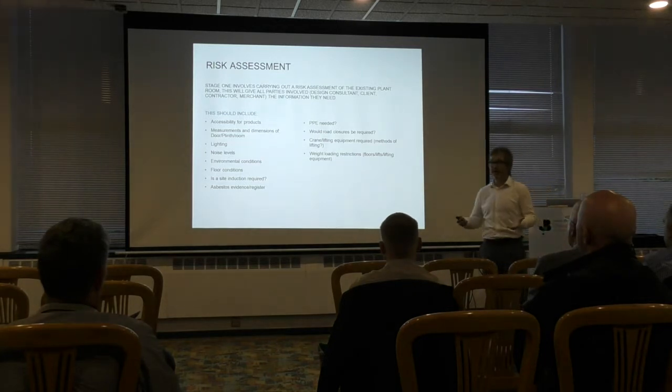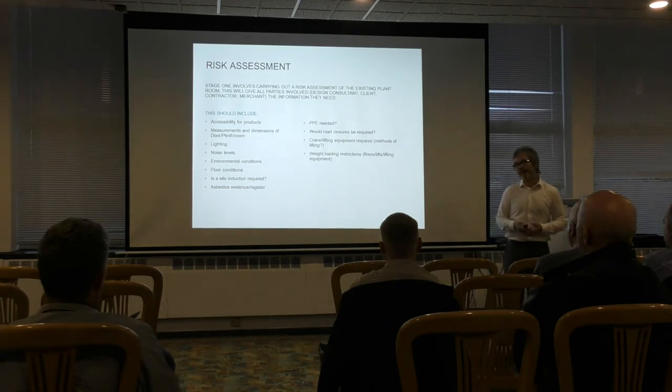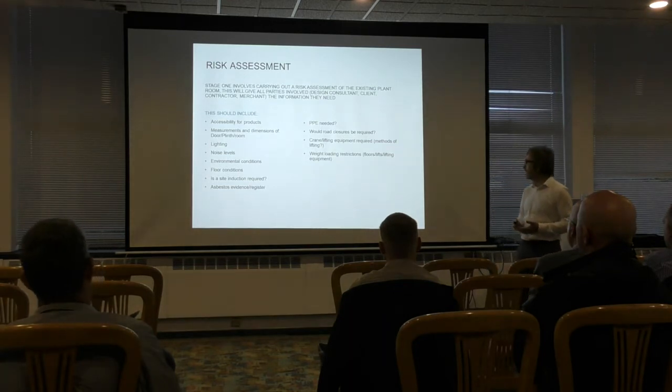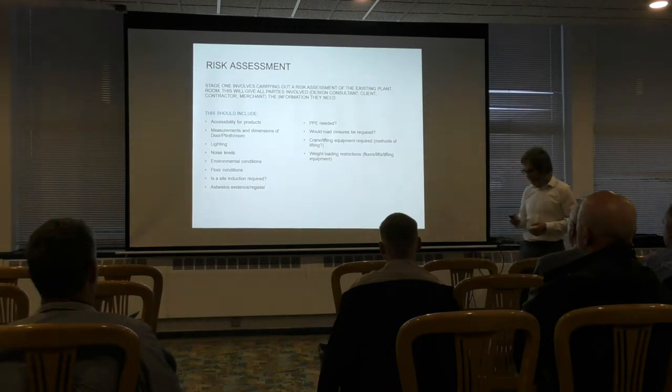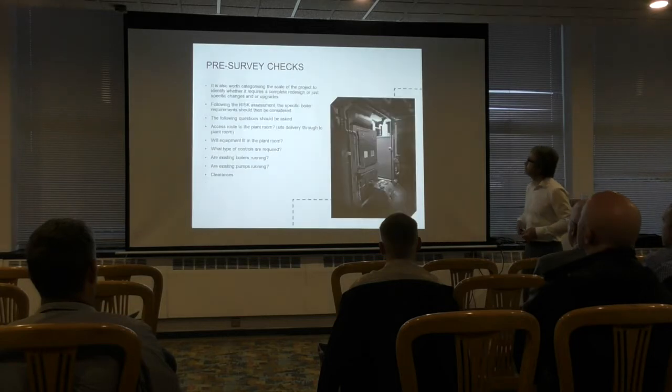It could be that we've got a nice goods lift, but maybe the goods lift isn't man enough to take the boilers that we're proposing to put in. But also, the floors along the way, there may be mezzanine floors that we need to be aware of that have got loading restrictions on them. And look at the checks themselves.